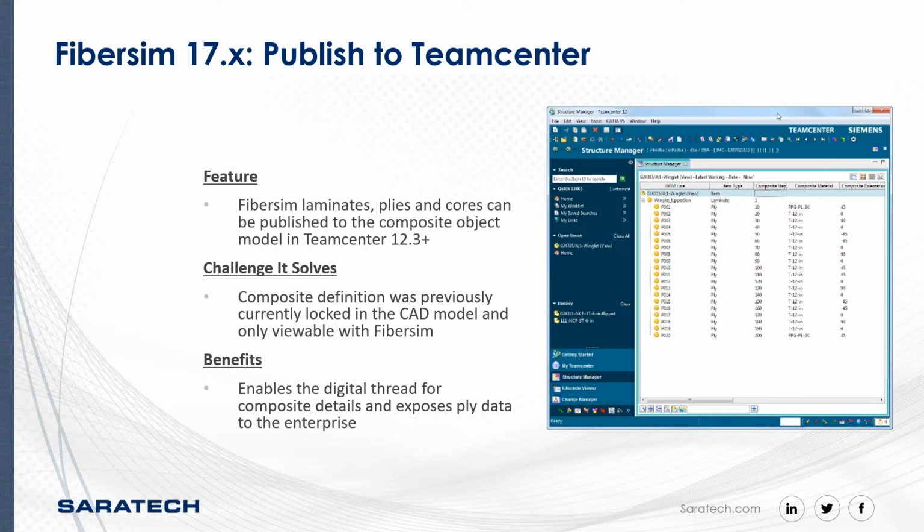Another thing we've done in the Fibersim 17 releases is we've added a publish to Teamcenter option. For those of you that are using NX with Teamcenter in a managed environment, we now have the capability to publish the composite object structure into a Teamcenter data model. Starting with Teamcenter 12.3, there's now a composite object model built